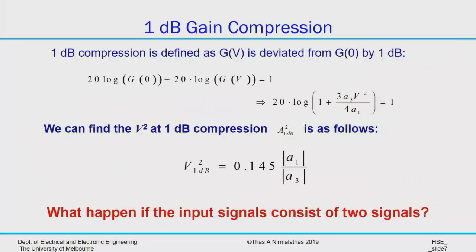So just to give you a little bit more on what we originally had, remember the gain of the stage we defined as G, and then I wrote down a function, for a given sinusoidal excitation, that was a function of input voltage. What it means is the linear curve is simply V equal to 0, that's G of 0, and whatever other arbitrary value differs only by 1 dB. So I'm just simply reinterpreting the definition of the 1 dB compression point in the first line, all right?